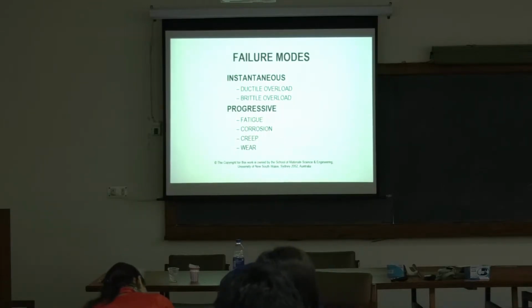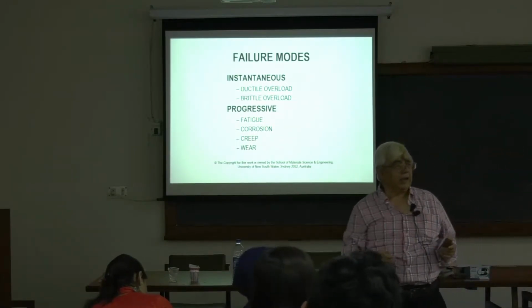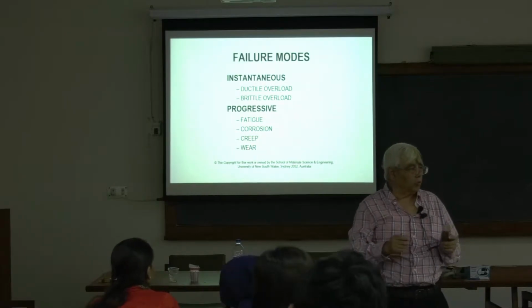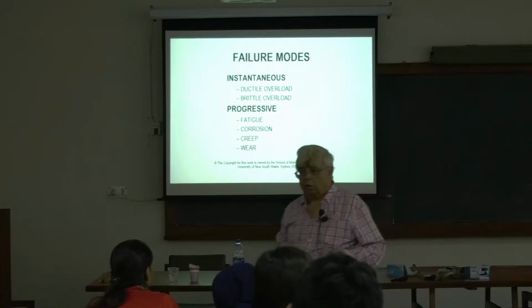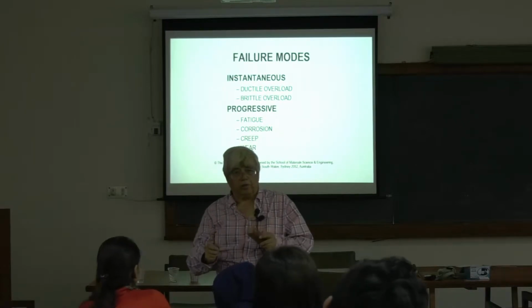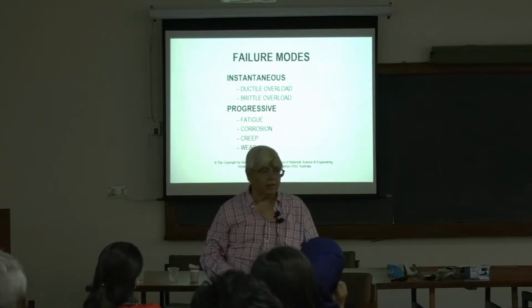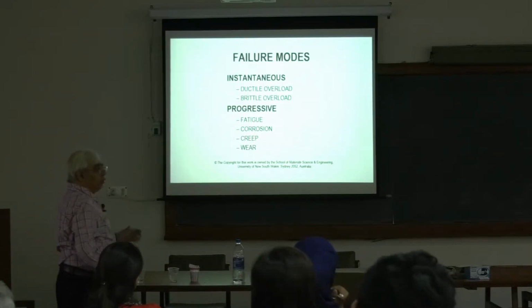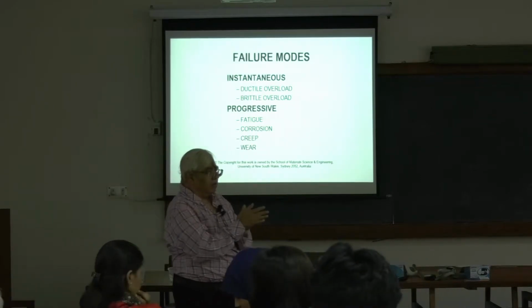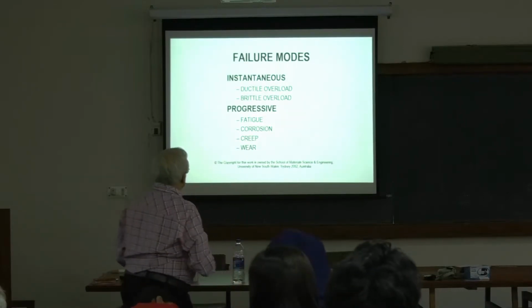So if there is a constant load on the material and there is a void, that void can grow over some time. And that's why all planes and structures have regular inspection of their composites. Maybe every 3 or 6 months, the plane is put in a checking chamber. With non-destructive testing, things are so much easier. Non-destructive testing is very useful. And what is wear? Wear is when two things just rub against each other. That generates scratches and things like that. So these are failure modes.